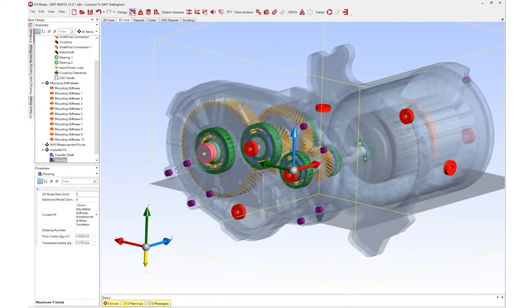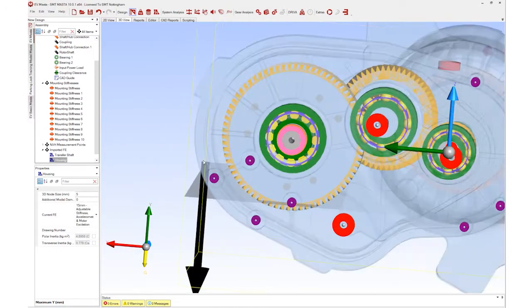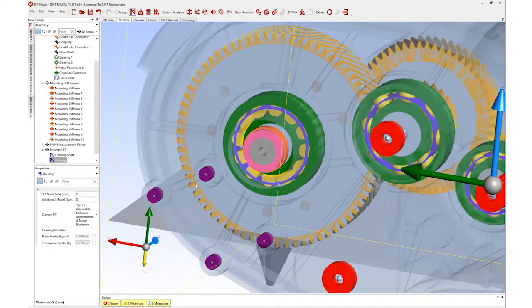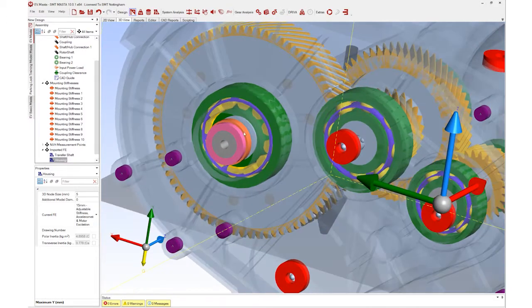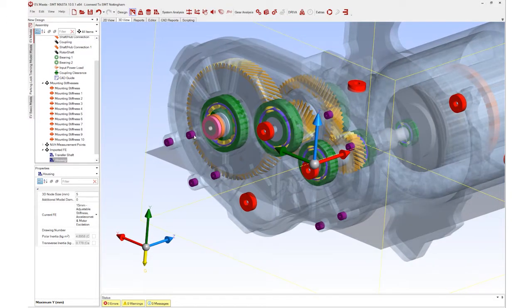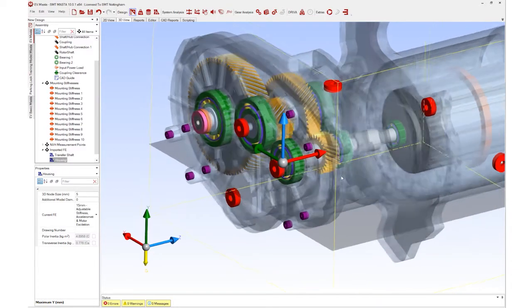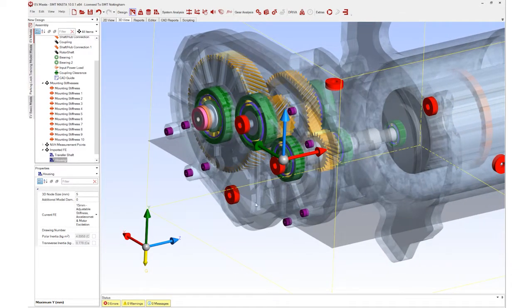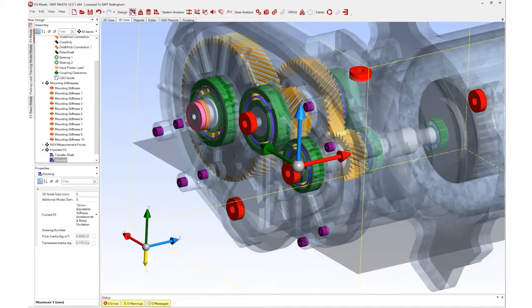So you'll see at each of those points where we saw the grounding points a moment ago, in this particular case, we have a rigid bond component at those points. So a rigid bond component was designed classically for internal components within MASTA, so connecting things together. However, we can use them as mounting points. There's a couple of ways we can make them.